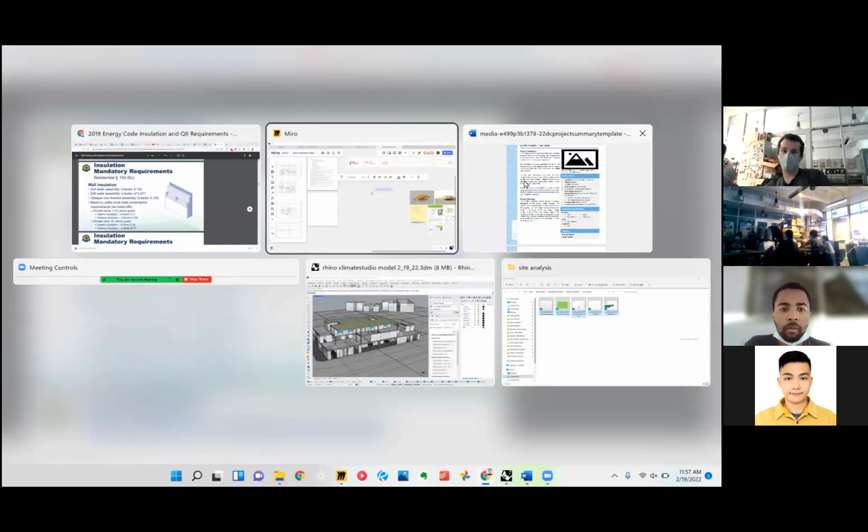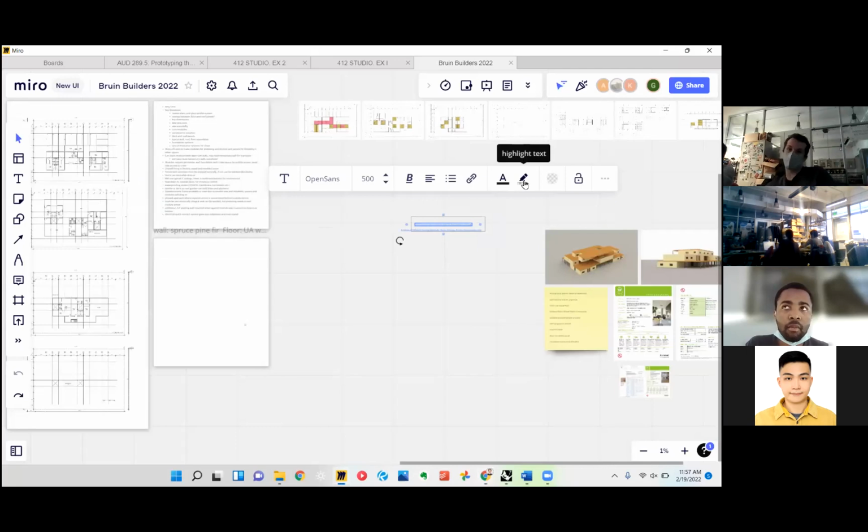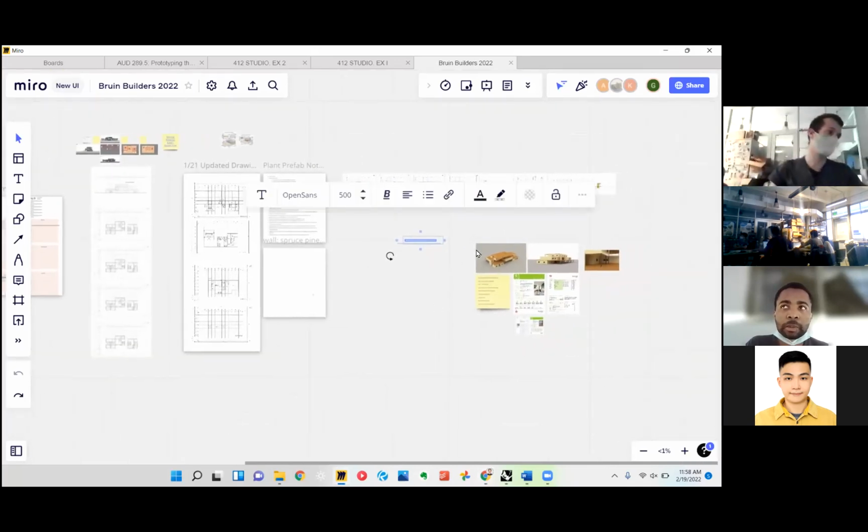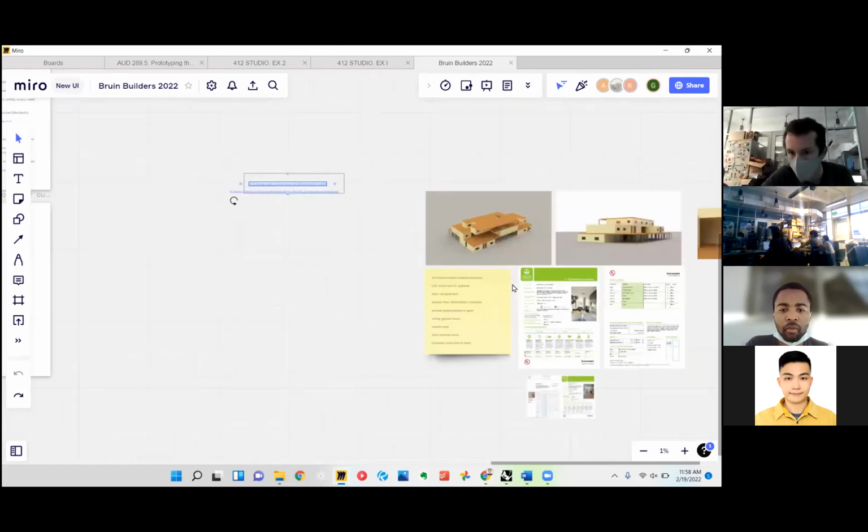I remember when we were talking with the plant prefab, we were talking about 2x6 walls, right? But with no exterior insulation, a 2x6 stud wall, with I think it was just drywall on the inside and some sort of cladding on the outside. Yeah, so pretty basic. Could we just go with something like that in terms of the final materials?